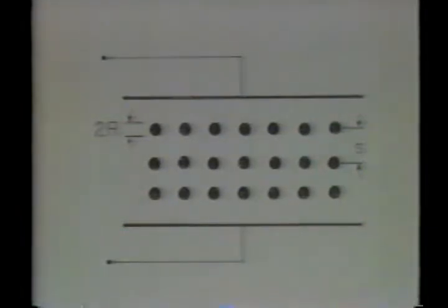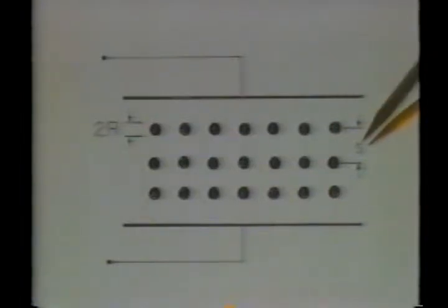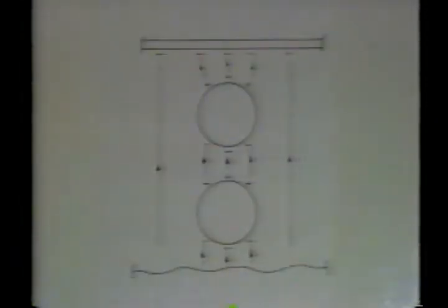In addition to the uniform field, due to the applied voltage, the field outside the spheres also includes the dipole fields from the array of spheres. The spheres, like the molecules of a material, are polarized by an applied field. The artificial dielectric is composed of an array of ping-pong balls with conducting coatings.